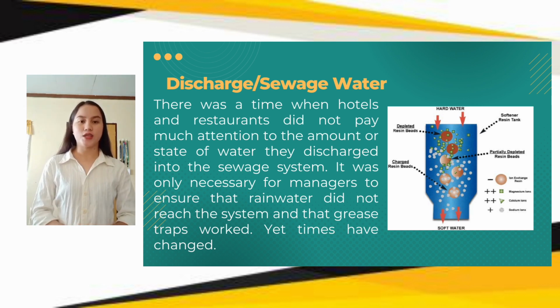The ion exchanger, like the filter, has a granular material bed, a flow distributor, and an influent vessel that collects the product. Green sand, aluminum silicate, synthetic siliceous gels, bentonite clay, sulfonated coal, and synthetic organic resins are examples of exchange media.